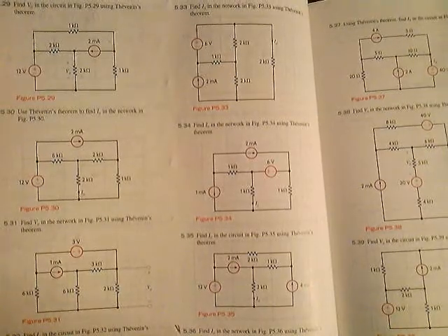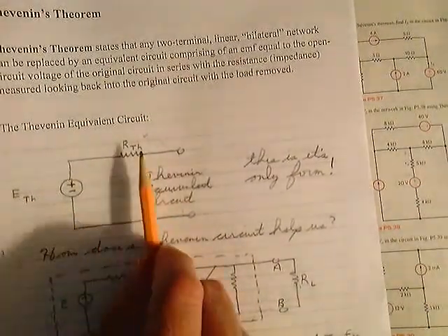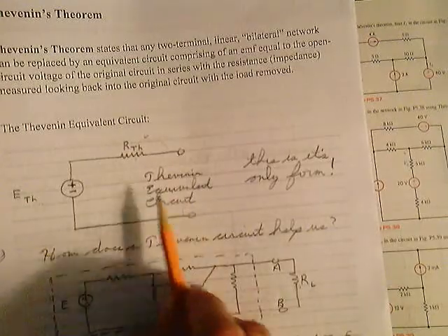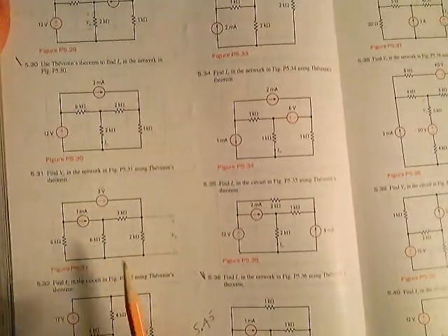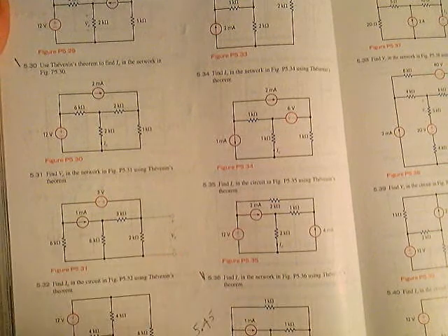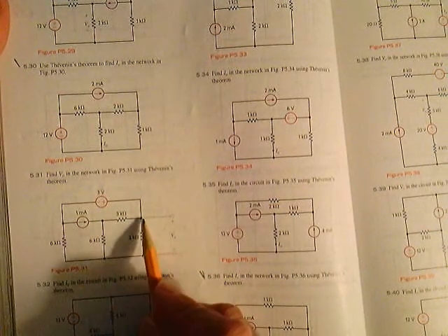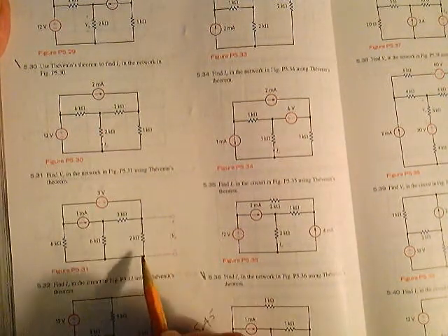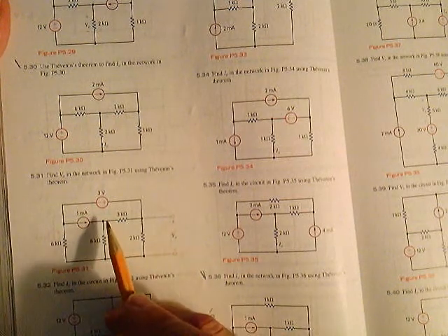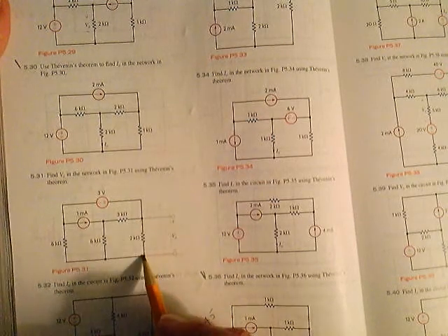And I think you'll see that if you know the value of E Thevenin and you know the value of R Thevenin, and you put that resistor back on, you can calculate I/O, the current through that resistor, simple series circuit, very easily. How about down here? They want you to find V out using Thevenin's theorem. So you're going to remove this resistor. That makes this the load resistor. Just like this I/O made that the load resistor. You're going to remove that resistor, mark the terminals, look back in, find the Thevenin resistance, calculate that open circuit voltage, put it back in this form right here.